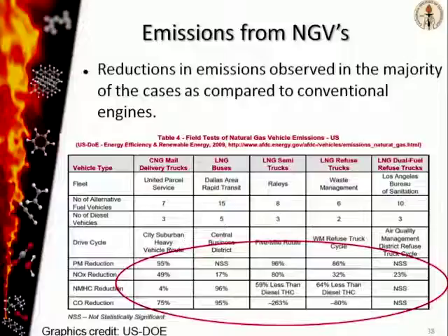There were a couple of cases where you saw an increase in the amount of carbon monoxide in heavy duty trucks which operate at high loads, and this is something I'll be discussing in one of the future slides. But for the most part, you can achieve a pretty good reduction in emissions by switching over from diesel to natural gas based fuel.